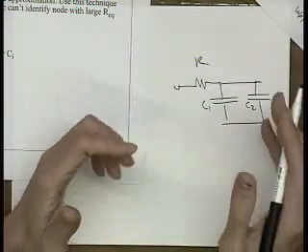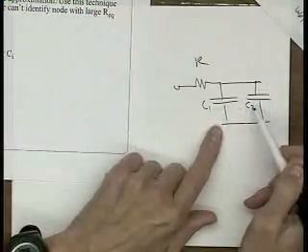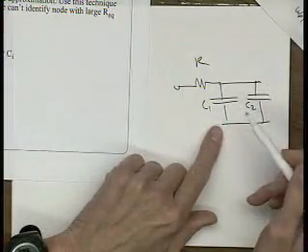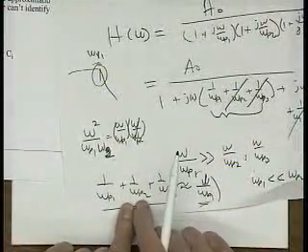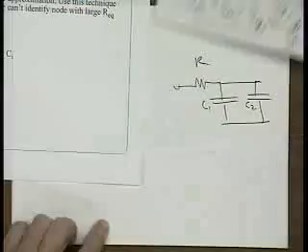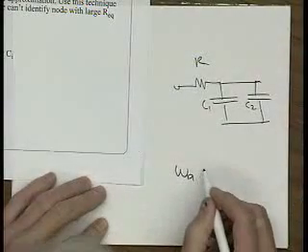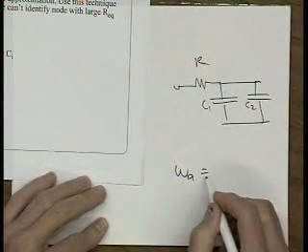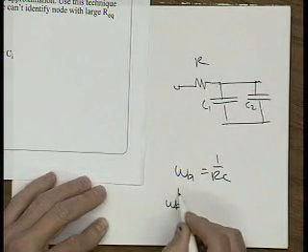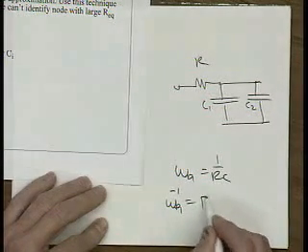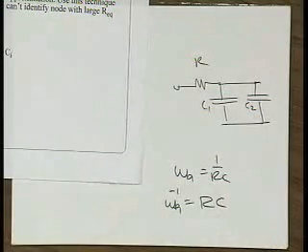So it's not necessarily true that each capacitor gives rise to a separate pole. But because we're working with the inverse of the pole locations, omega p1 is effectively 1 over RC, so omega p1 inverse is equal to RC, the time constant.